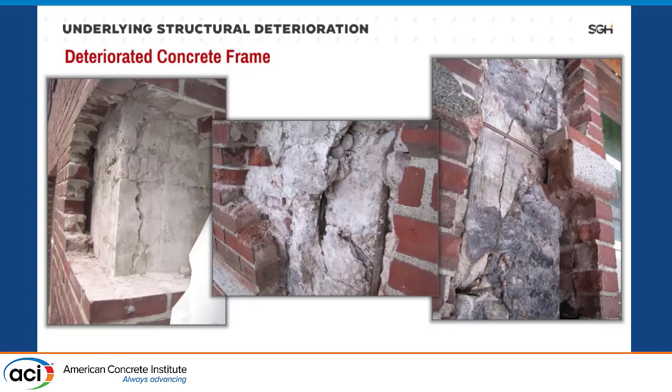this photo shows the deterioration of columns at different stages. First, you see here the initial cracks at the reinforcement, indicating that the reinforcement is corroding and expanding. Then you see the spalls and the delamination, and as they deteriorate, it starts pushing out the masonry, first causing cracks, and then the masonry eventually can become loose and become a fall hazard.